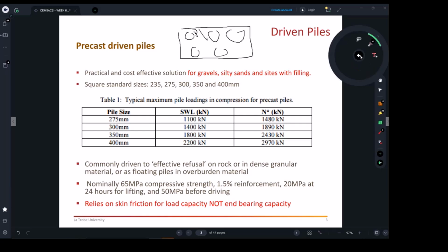So the contractor who will be doing the piling, they are engineers as well. They have their own engineers, who, with their equipment and hammering facilities, will end up doing tests for each pile to make sure it has actually stopped and cannot go any more into the ground, and that it can resist these figures. So that's how it works.